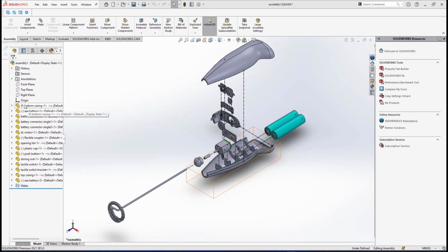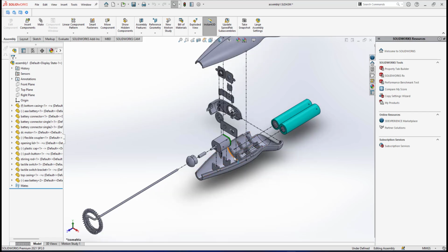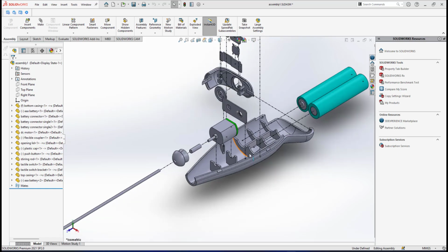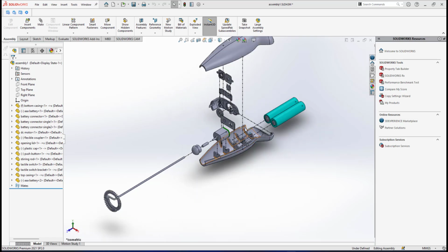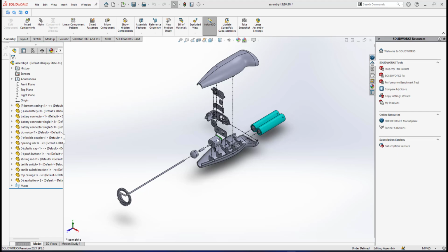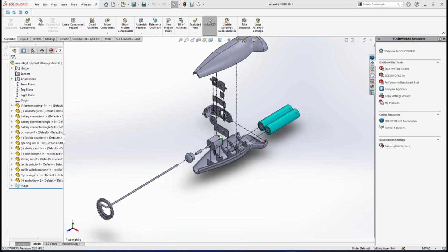But when we look at it, the order of this listing is not in hierarchical order. What I mean by not in hierarchical order is that the order of this listing here must follow the order in which we will do the assembly. Alright, because it will affect our assembly drawing and also the exploded view drawing, because in the assembly drawing and exploded view drawing, we have balloons and we have a bill of material.